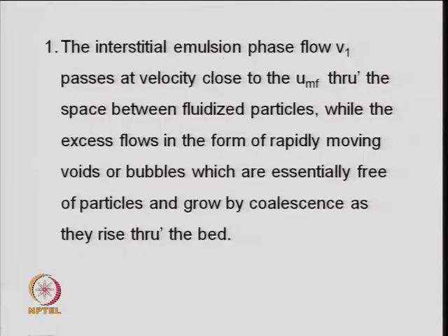Some salient features when you look at the design: the interstitial emulsion phase flow, V1, passes at velocity close to the minimum fluidization velocity. Because I told you that in the emulsion phase the solids are all together, while in the bubble phase the gas is there, more gas. Reaction is not with the solid alone; reaction is when the gas contacts with the solid. So, this is one important thing when you have a 3 phase model.